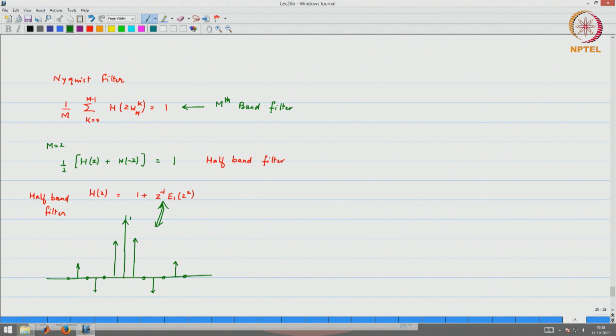Now, may I ask you a question, which may seem a little bit trivial. What can be the order of a half band filter? Again, it all hangs together. There is a 0 valued coefficient. If I want to look at the non-zero values, supposing I take up to the second non-zero term, it is some odd number, because I can always leave out the last one.